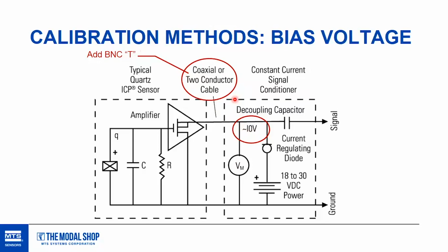It's kind of neat. They're proportional to each other, and it's a good indicator if you have damage to that hermetic seal on the can. If moisture's getting in, the sensor's going to effectively breathe, and over time it's going to damage the components inside the sensor. So paying attention to the structure, the seal on the sensor, can be done through bias voltage measurement.